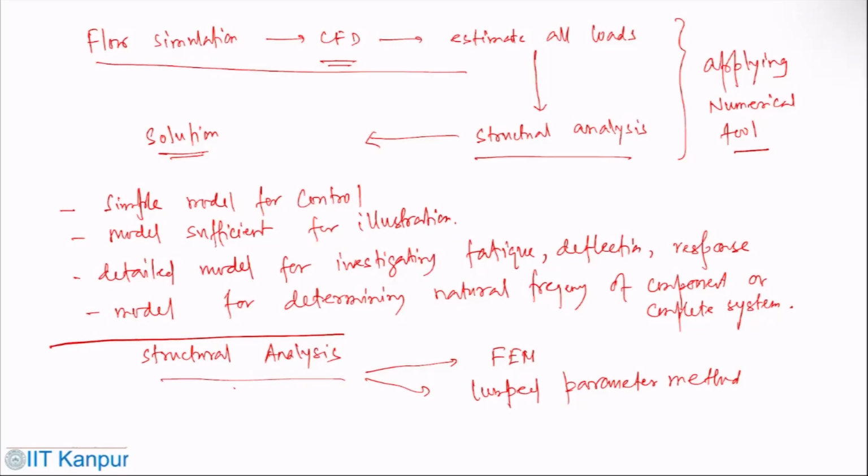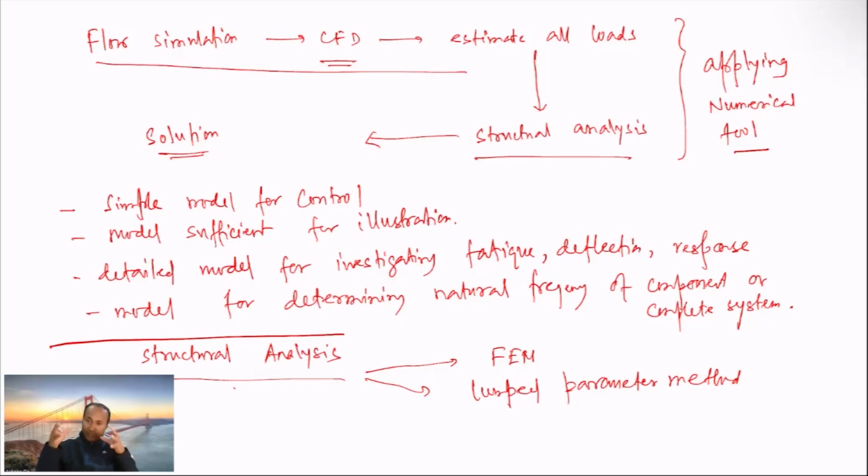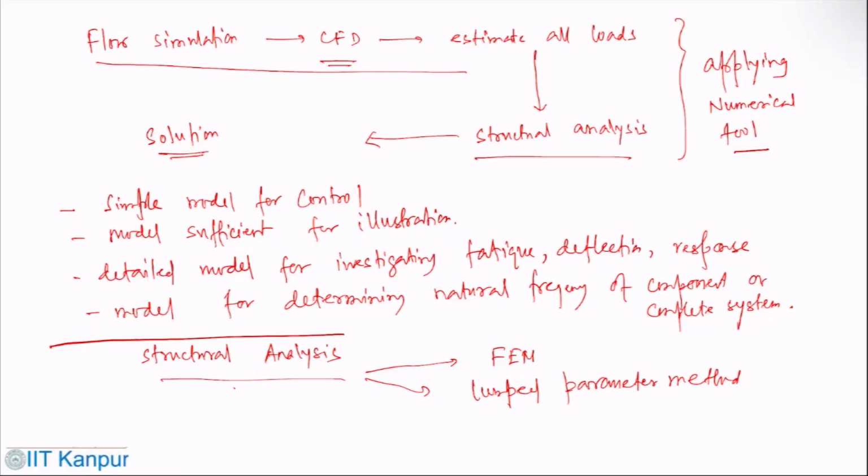That means you can consider different components and use their stiffness or inertia as lumped parameters in a simplified analysis. That is obviously cost effective compared to the finite element method, but it is better than a simplified linearized system. Okay. Now we can have modal analysis.